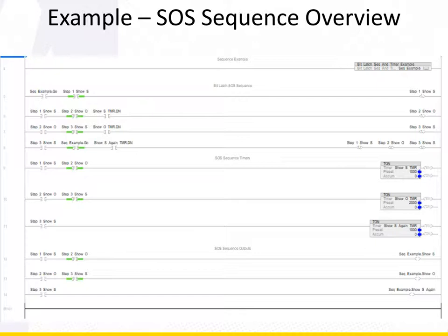See, this is what I mean when I say there should be a logical and consistent grouping of rungs. Each of these is a rung, as you know, and you can see the logical reason for why they are grouped together as they are. When I say grouped, you can see that the groups are interrupted by rung comments. And so the rung comments are placed to describe the group.